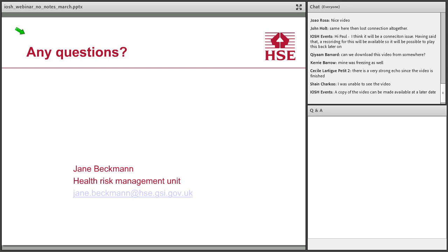Right, let's look at another one. On the window case study, I'm reading this straight off. How do we offset the weight of the windows against doubling or quadrupling the trips up and down stairs? Which action do you see as the most risk? Yeah, that's an interesting one. Well, to be quite honest, obviously the best way was actually to get the windows delivered straight up onto the floors in the first place mechanically. Had people thought about it, then the windows could have been put in through the openings, but that wasn't done.